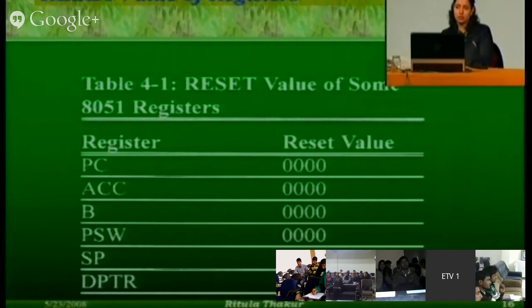That is the reason. So this is the main reason. Otherwise what will happen is that if you do not specify ORG 0h, it will take any location and start writing your program. But while execution, it will take by default the address in the program counter, because program counter contains the address of the instruction which is to be fetched first.